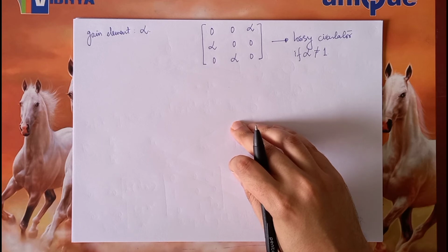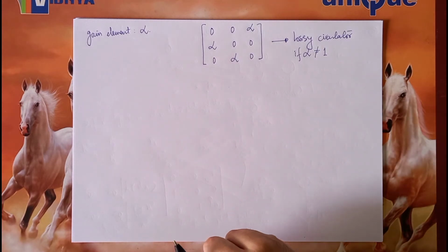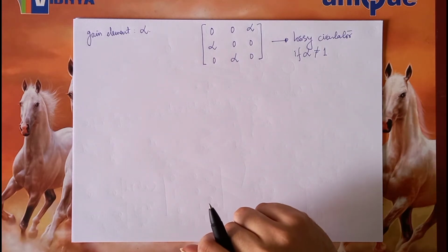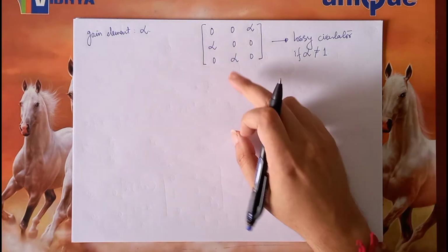With this backdrop and discussion and understanding of 3-port networks, where we essentially made use of a number of techniques to analyze them, in particular, to analyze the Wilkinson power divider, we saw that the analysis was initially very tricky because of that triangular shape formed due to 2 connecting transmission lines and 1 resistor.